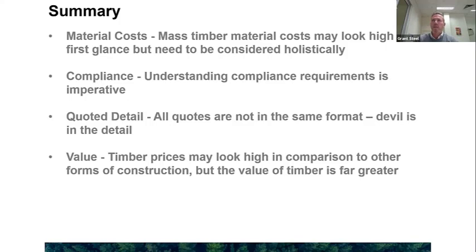Otherwise it's going to be up to a third party to demonstrate that the manufacturer's standards, wherever it's been made, would meet the requirements of the Australian standards. If you can't get that process to happen, then you're into some significant costs for testing here locally. A typical cost of AS 1530 testing is probably between 15 and 30 grand. And the other thing to bear in mind is it's not going to happen overnight either.